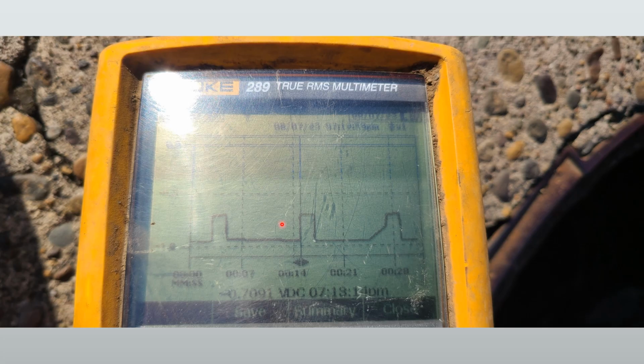And this is what an instant off measurement looks like when practically applied out in the field. We have the on reading at the bottom. We have the moment that the CP current is interrupted. Then here is our true level of polarization. So we want this value right here, the moment that the CP current is interrupted. Usually I'll run about 10 seconds on, 1.5 seconds off to make sure that I get enough resolution on my meter. I use a Fluke 289. It can capture the waveform. This was 3 cycles of measurement, about 30 seconds.